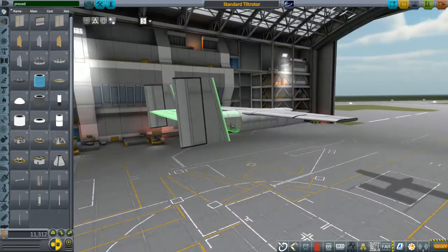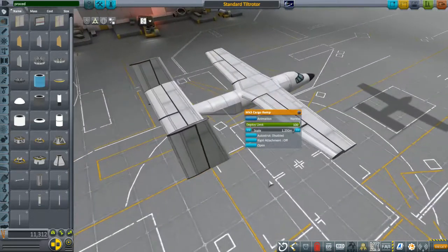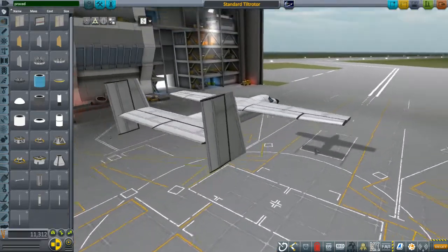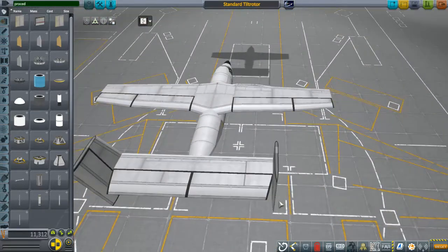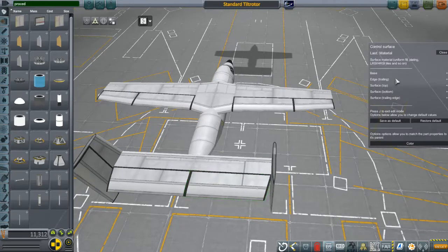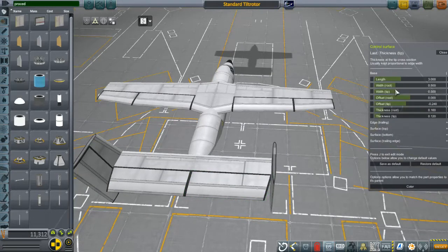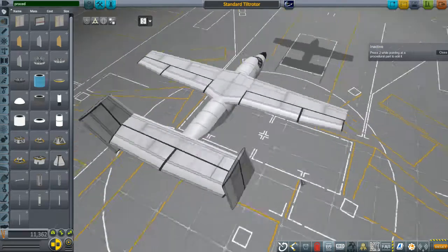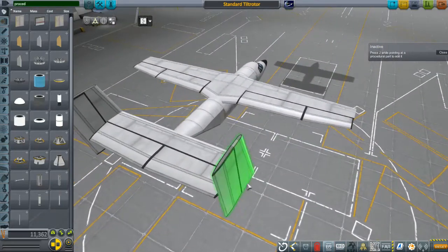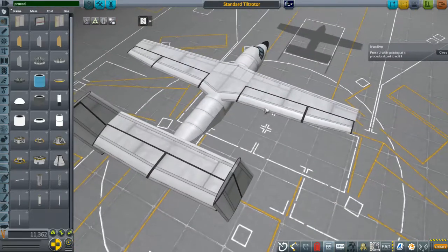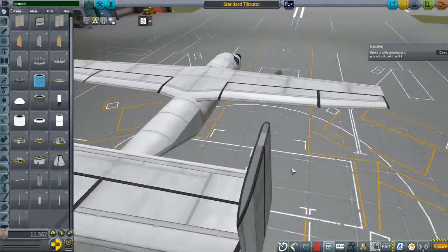Now I can still see just some slight misalignments here and there. I'm not too concerned about those at this point. They look pretty decent. I might mess with this flap a little. Base. Let's see. Width root. If I make width root, it's going to give it kind of a triangular apex. And since we're right here, before we start working on the engine pod assemblies, I'm going to go ahead and start walking through configuring each set of wings for their job.